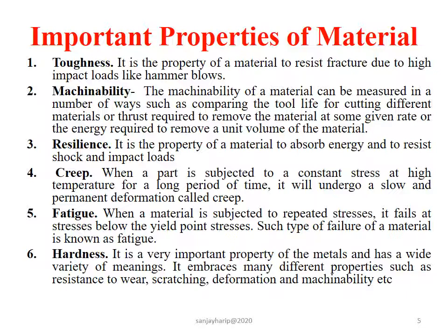If material is subjected to constant stress at high temperature for longer period of time, it will undergo a slow and permanent deformation, which is known as creep. This property is useful for selecting material for IC engine, boilers and turbines.